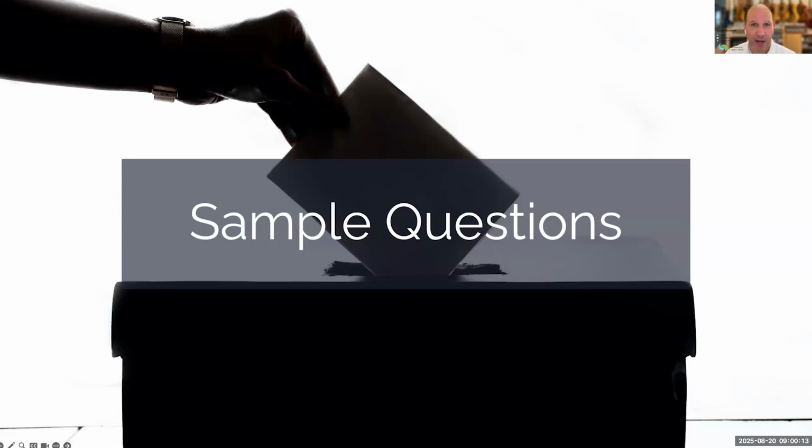All right, on to the next question. This will be quick. I'm going to give you 10 seconds to answer this. What is scouring velocity? What's that minimum velocity that we talked about early on? Is it 2? Is it 2.5? Is it 8? Or is it 10? So yes, it's 2 feet per second. 2.5 is sometimes considered the ideal, but the minimum is 2.